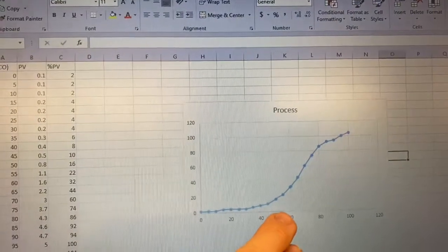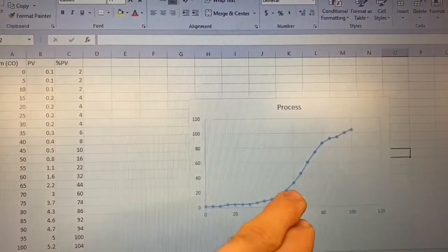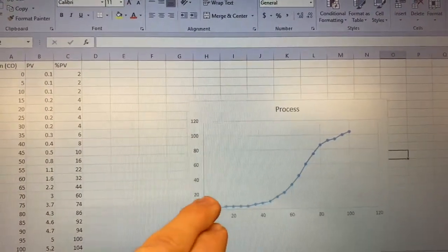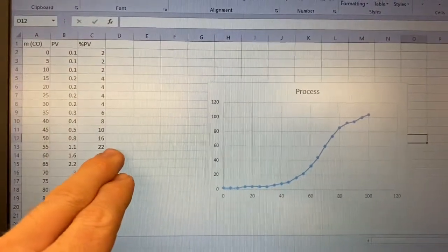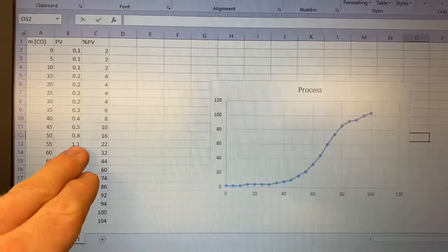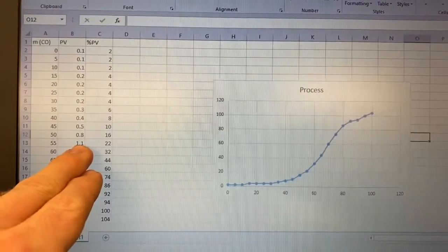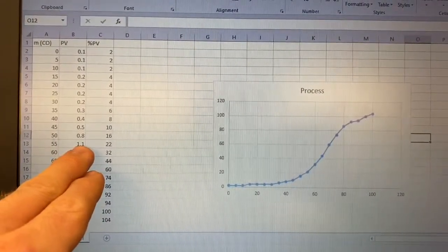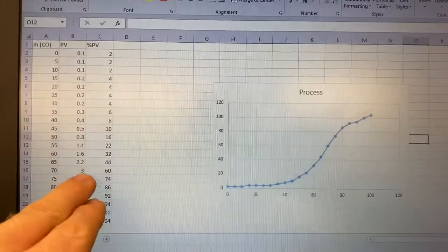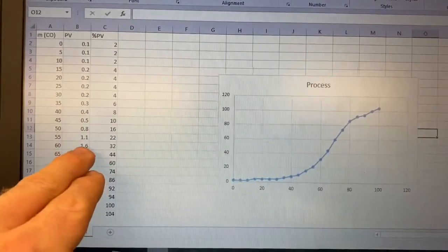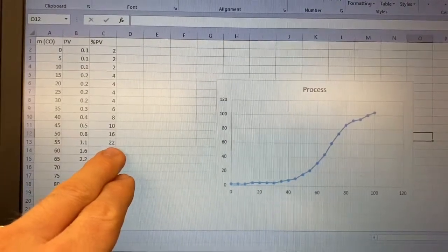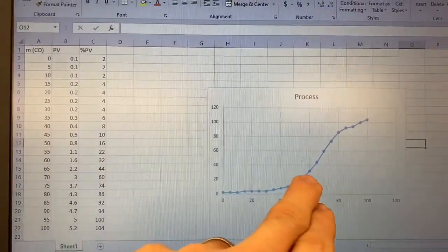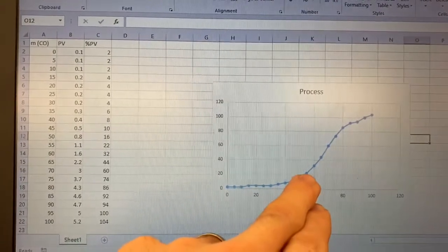So it appears that about somewhere around 20%. So let's see, when our process variable is around 1, that looks like a good starting point to switch over to the other tuning parameters. So we're going to be referencing the process variable. So when our PV is around 20% here, looks like around 20, 22.